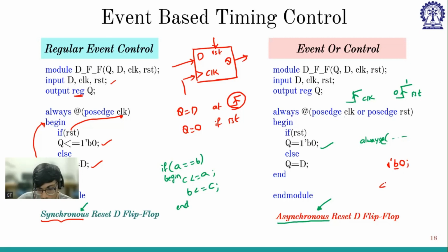Say I'll write 4'b. It means 4 bit binary, so I have to specify 4 bits: 0, 0, 1, 1. I can write 4 bit decimal, and the decimal value is 10. So this 10 can be implemented using 4 bits. So in decimal, I'll write 4'd2.